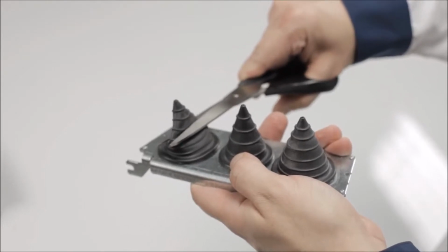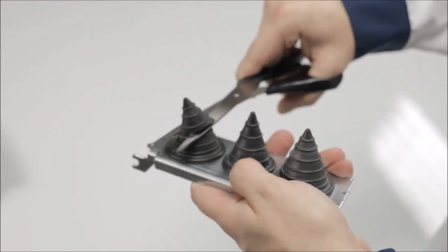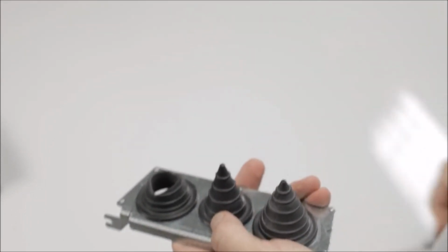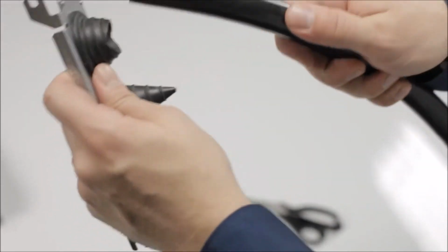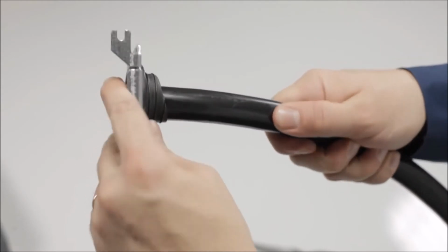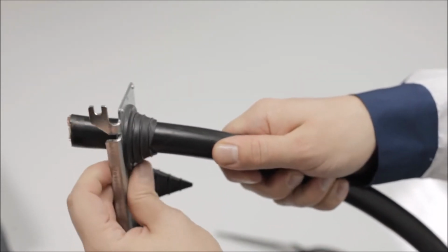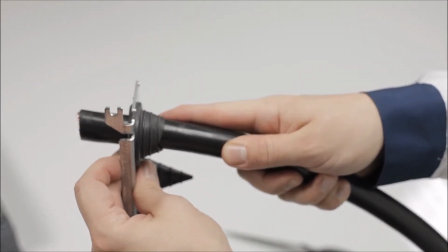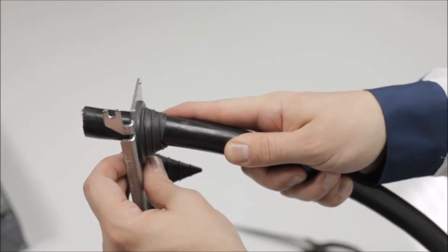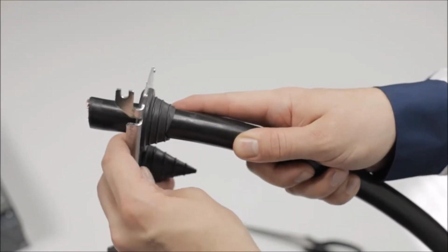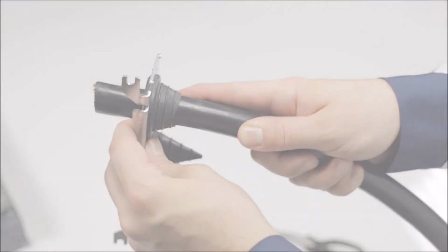Since you will need to do the sealing yourself, it's important to know how to do it in a way that ensures the sealing is airtight. The cable grommets need to be cut open enough that they just allow the cables to pass through them without letting anything else reach inside the drive. The second notch from the tip should be fine for this. Once they're cut, pass the supply and motor cables through the grommets.